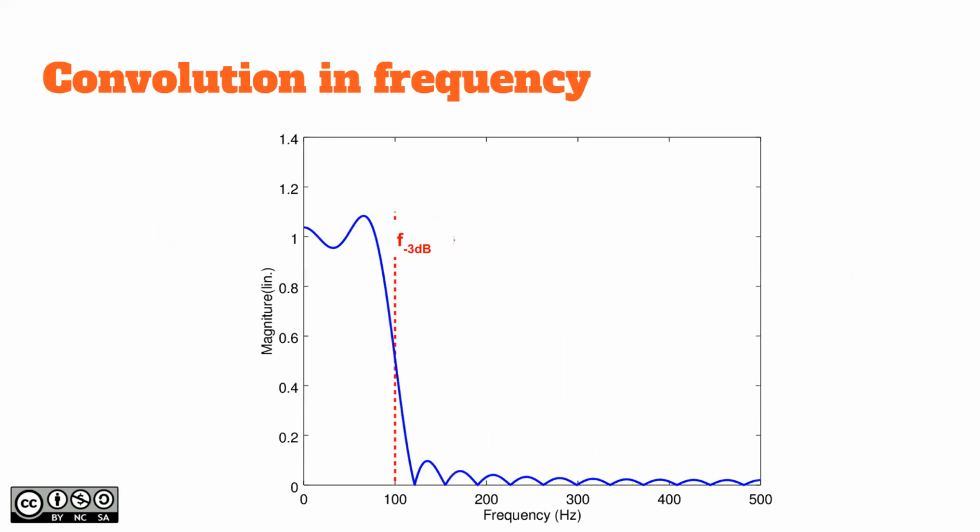So the end result is that this is showing the convolution between the box, which defines the minus 3 dB point here, and the Z transform of the box. So sinc gives the minus 3 dB point, and then the box gives that kind of variation here.